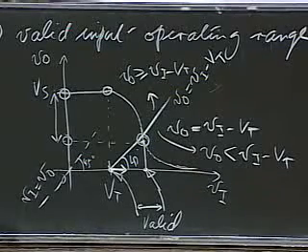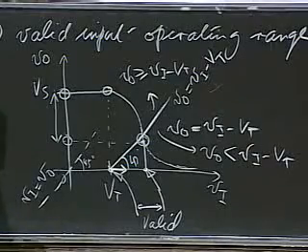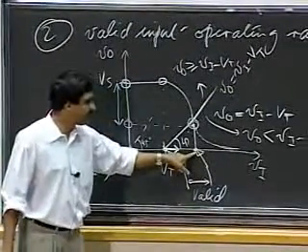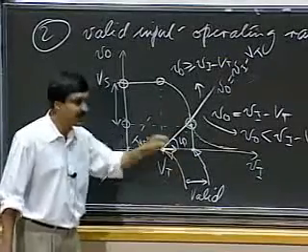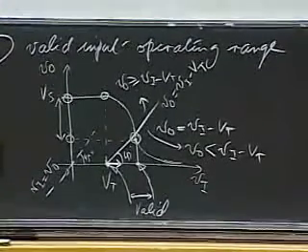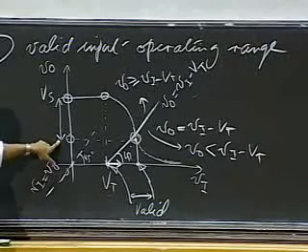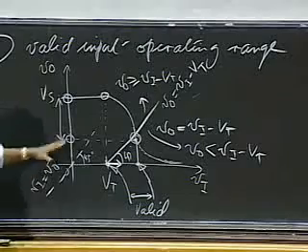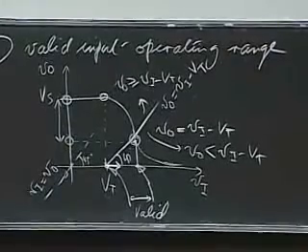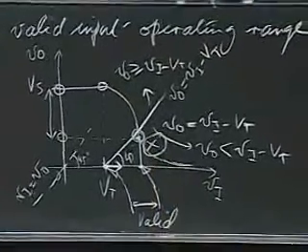What this is saying is that if I, as the designer of the circuit, am disciplined enough to apply inputs in this range, VT to some value here, graphically shown here, then my MOSFET will remain in saturation. And correspondingly, my outputs will go between VS and some value here. Hopefully that gives you some of the intuition behind how we get it. Let's continue. Let me label this point X.